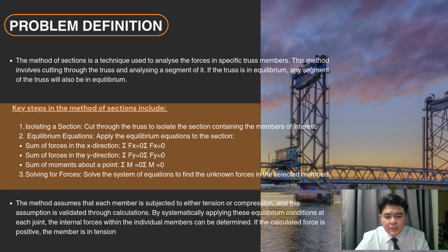By methodically enforcing equilibrium conditions at each joint, it becomes possible to identify the internal forces in the individual elements. A positive computed force indicates that the member is experiencing tension, while a negative force value signifies compression.